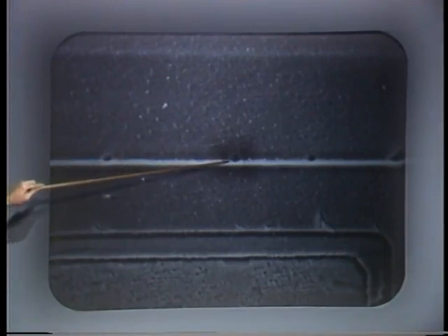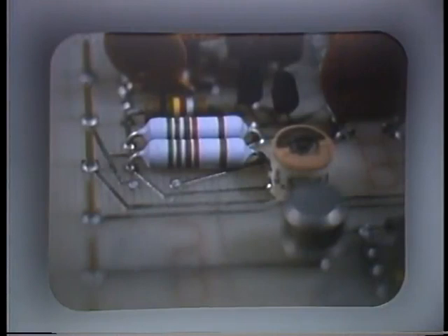Here is a photograph through the microscope of the line between a metal area and an oxide area, and you can see several small craters, each of which was made by a static discharge. If we increase the magnification, you can see just how spectacular these craters are. The items in the middle are bits of molten metal, which was generated by the discharge, and this whole crater is only about 1 micron across, but the parts are now worthless.